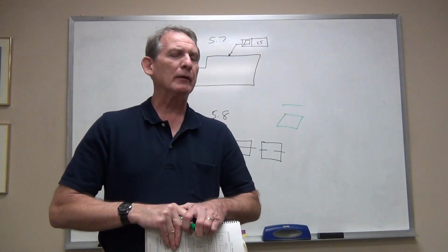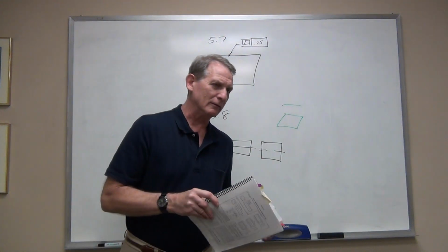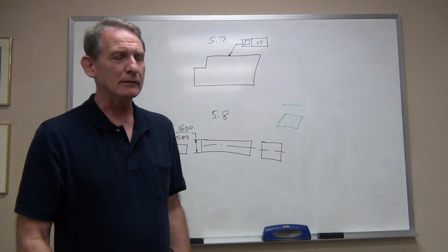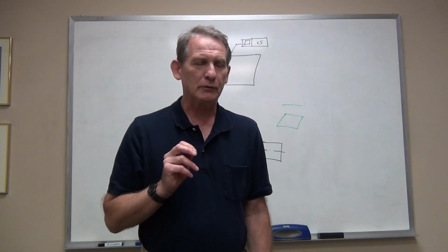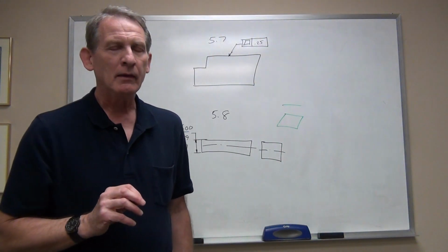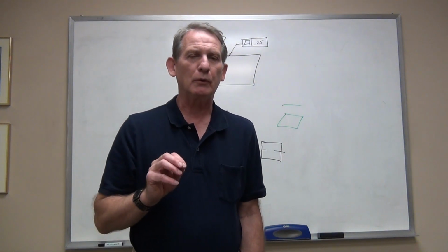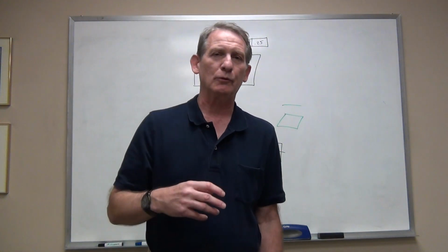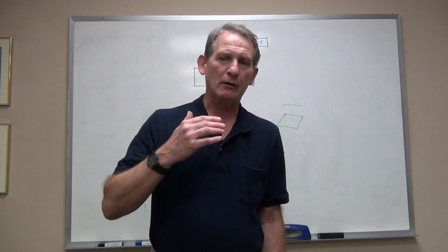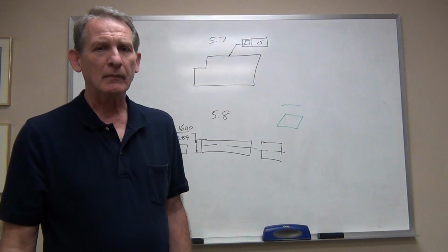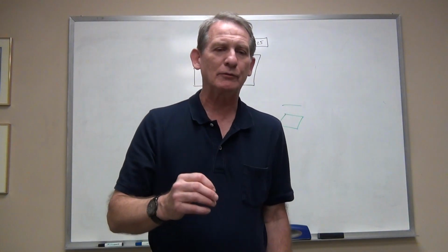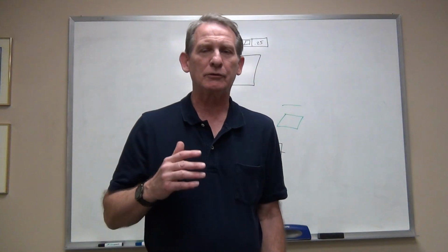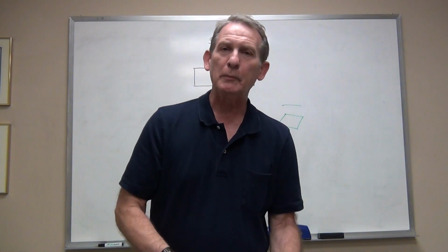And the real important thing to pay attention to here on these next examples and forever in GD&T is always being able to determine, based on the control and how it's used, the nature of the tolerance zone. Now, we've already seen a couple of different variations of a tolerance zone. We've seen parallel lines, and we've seen a cylindrical tolerance zone. Now when we get into flatness, we're going to start seeing another form, which will be parallel planes.